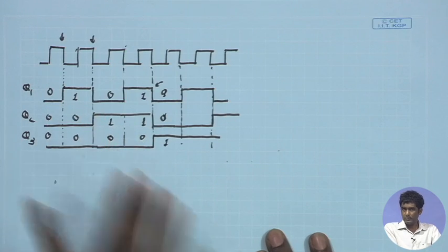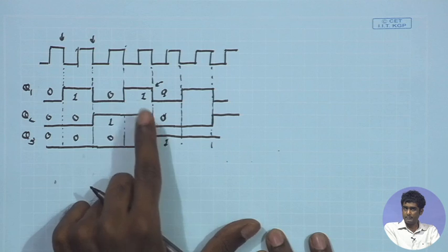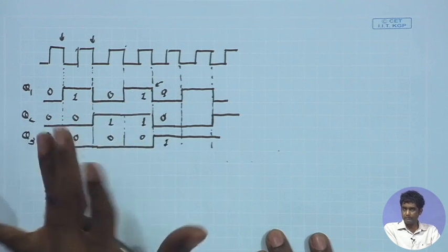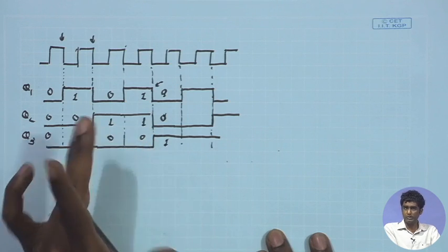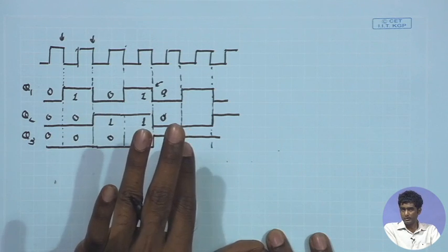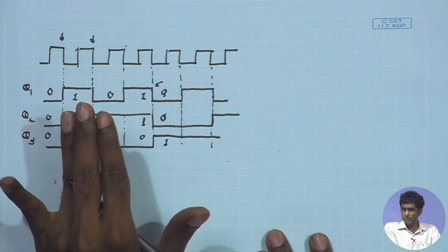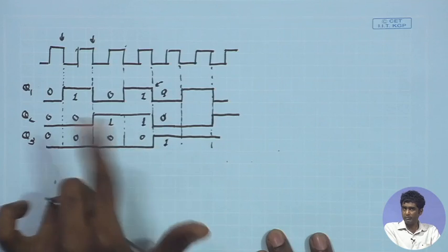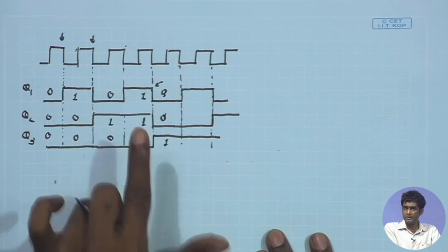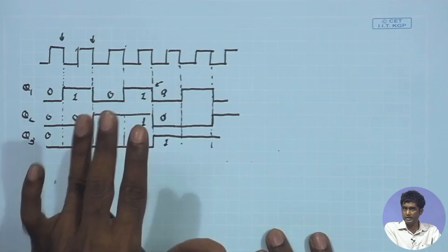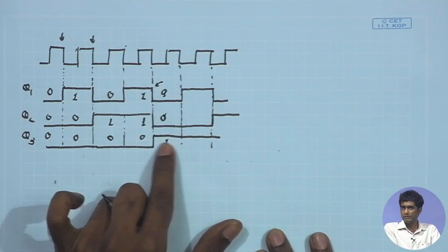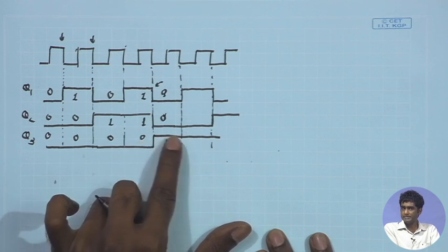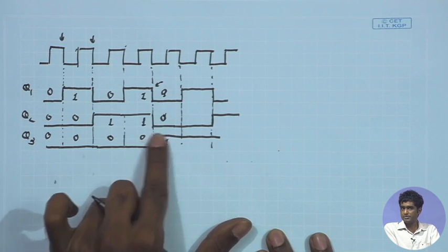And the other requirement is that at the negative edge of the clocks, these flip flops should be flipping their state. If the state was 1, it should be going to 0. If the state was 0, it should be going to 1. So, we do not need external data to implement that. What we need is the information about the previous state of the flip flop itself. If we know that state, we just need to make sure that the flip flop is acquiring the reverse of that state. So, if the Q3 output was available to me and it was 0, I want to make sure that the next time at the negative edge of Q2, Q3 is transitioning to 1.